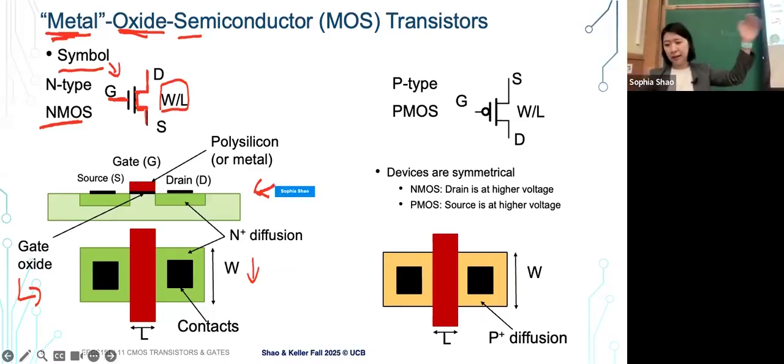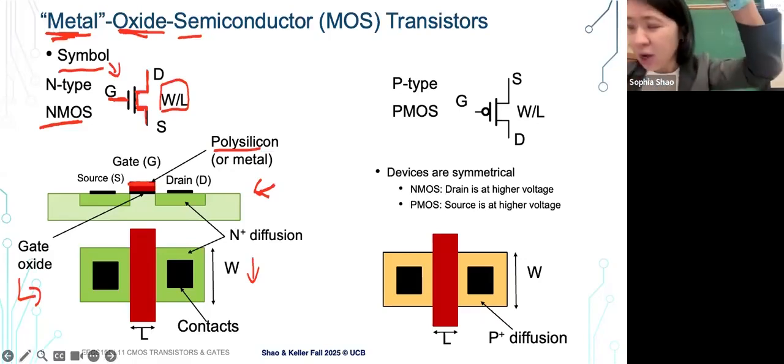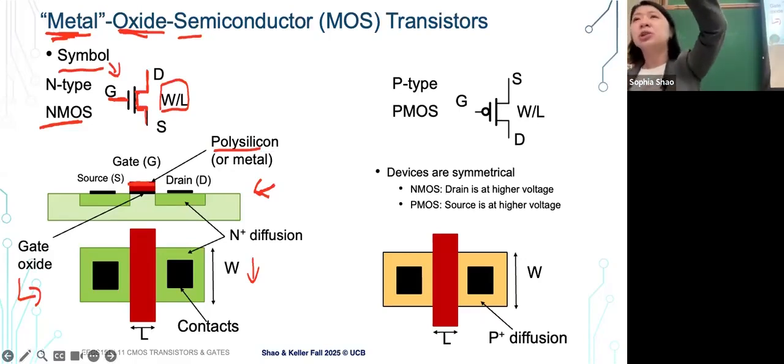We talk about the gate, I guess metal outside. The metal layer is basically referring to the gate layer, right? The gate is a controller, controlling whether things are on and off, right? Sometimes you also hear people talking about polysilicon. Those are different ways you can construct the gate here, right? So the gate is basically on top, to control whether the other two terminals can be connected or not. The other two terminals are basically symmetric, typically viewed as one being the source and one the drain, right?